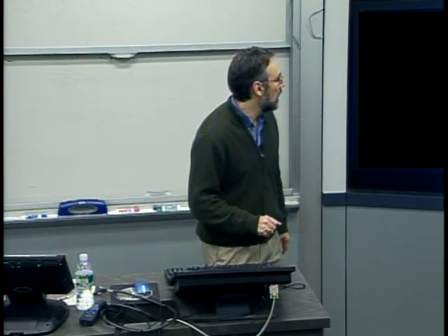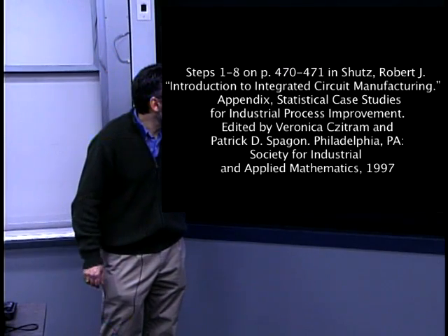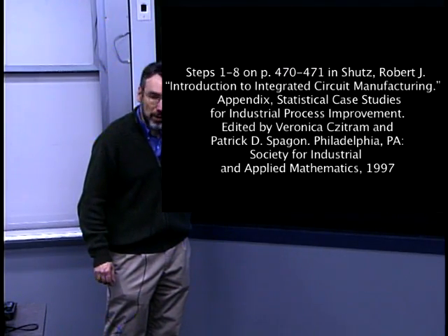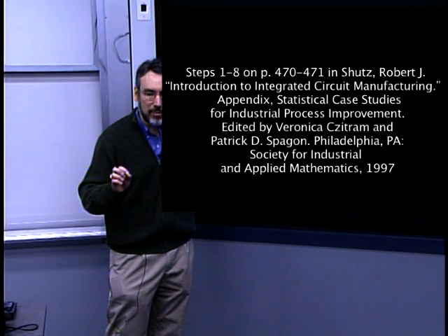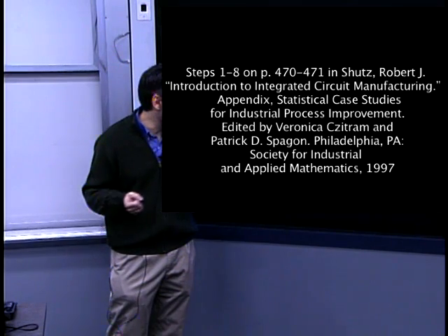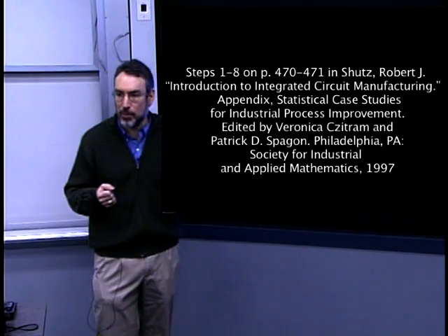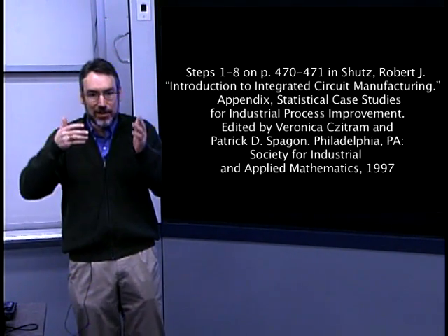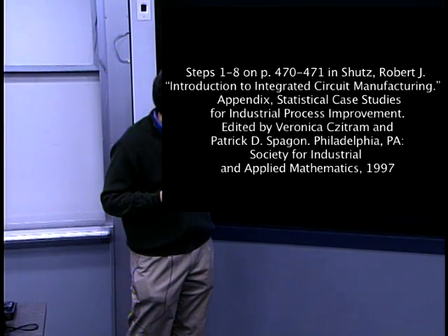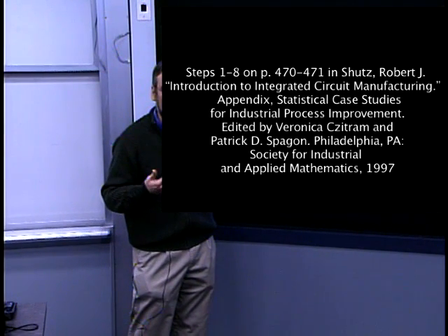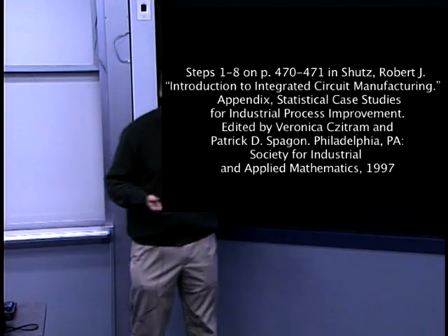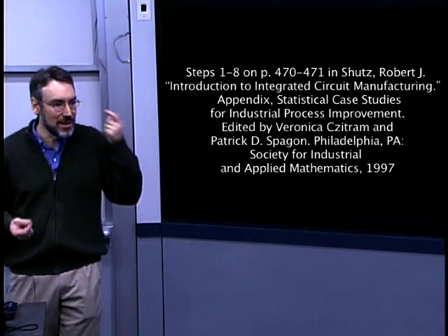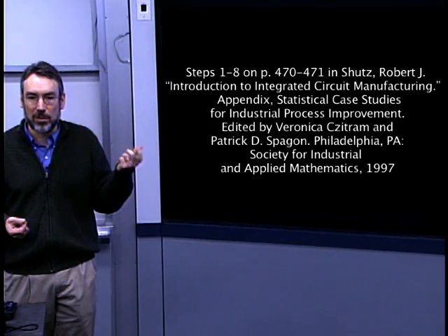Again, this will be fairly highly doped, either subsequent to the deposition or during the deposition. It is a semiconducting layer, but if one dopes it, that is, adds elemental impurities of a particular type to play with the band structure of the silicon, one can make that behave in a fairly metallic fashion. And in the MOS transistor, that polysilicon is very highly doped and is a conductor under all conditions.